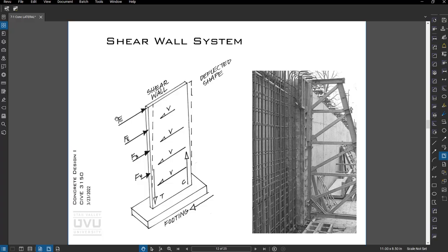So to size the boundary steel, we find the moment from these forces, remembering to use their full moment arm, and then divide by the distance between those two couples, or those two resultant forces.